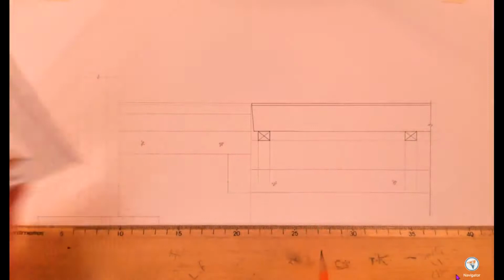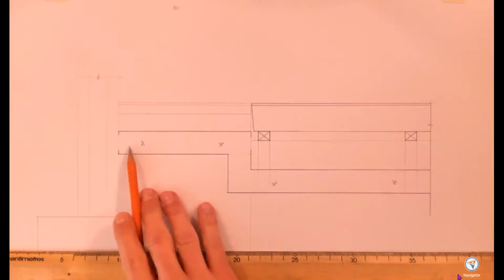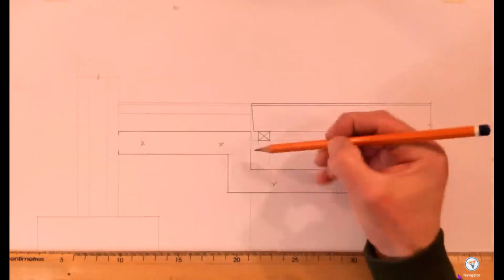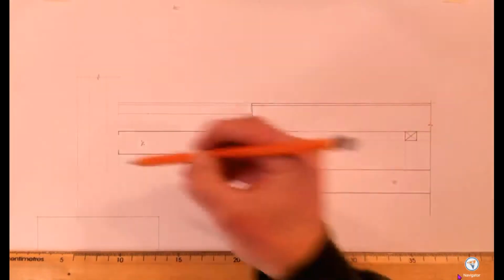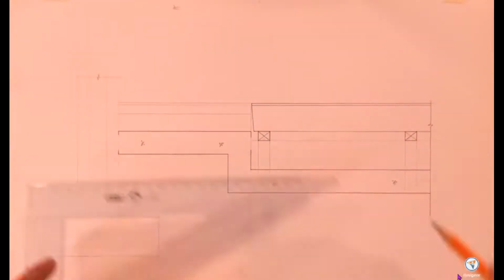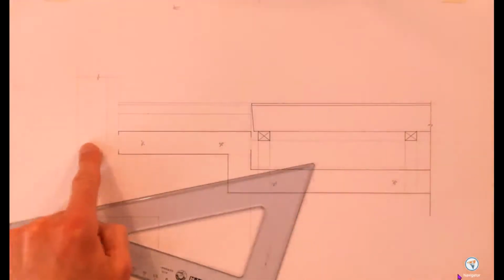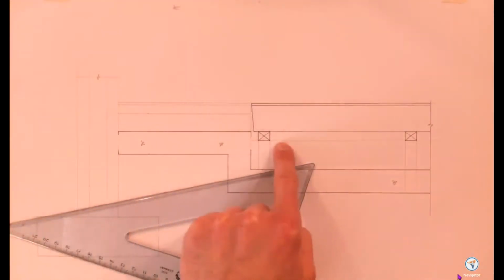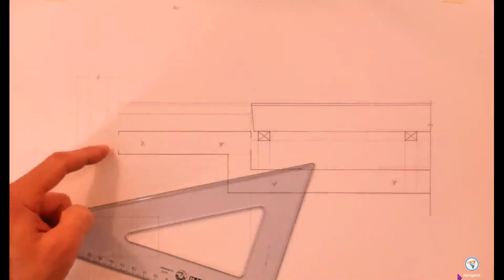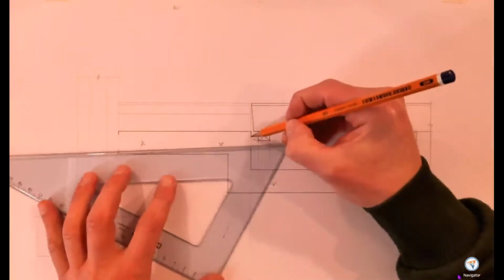So what I have now is this kind of Z shape, and I'll darken that in so you can see it better. So I've drawn in the shape of the subfloor here. I've left a little bit of this light and a little bit of this light. That is because we have to put in ventilation, as it said in the question. I need to put in a pipe that's going to run from the outside in through the subfloor and in here. And you're going to let air right in through the solid floor and then into the suspended floor.